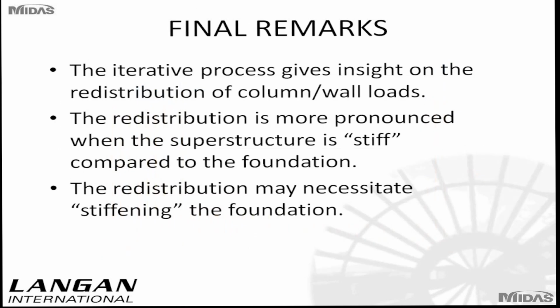So some final remarks. The iterative process gives insight on the redistribution of column and wall loads. Now this redistribution is more pronounced when the superstructure is stiff compared to the foundation. And the redistribution may necessitate stiffening of the foundation.